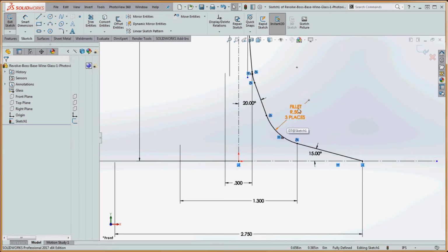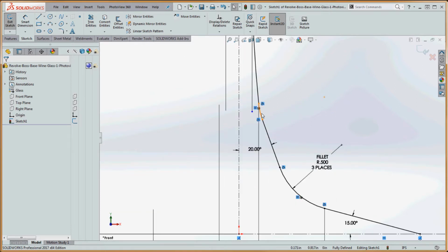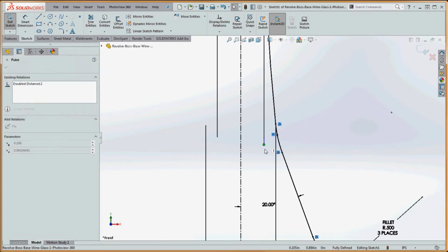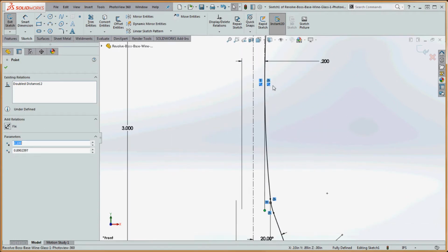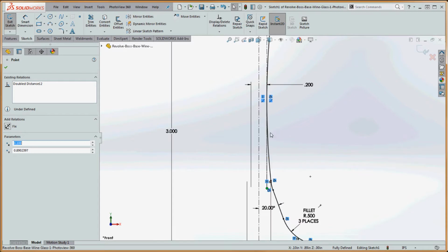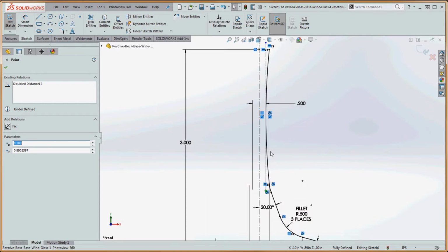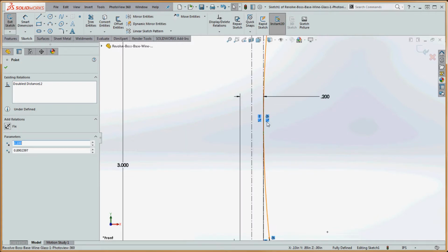Then after that we have a half-inch fillet. Another 20-degree angle on that. Another half-inch fillet. So there's that fillet. It appears in 3 places. That's the second place. And then over here I put in a center line. I made that center line tangent and midpoint to this really long arc up here. I never defined the arc. I never put a radius dimension on that arc, but it's defined by this center line at that tangent and midpoint relationship, and it's vertical.